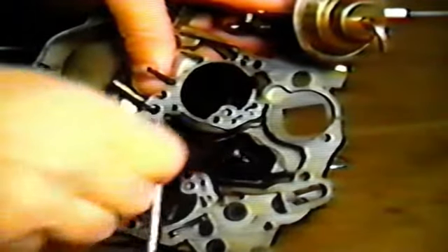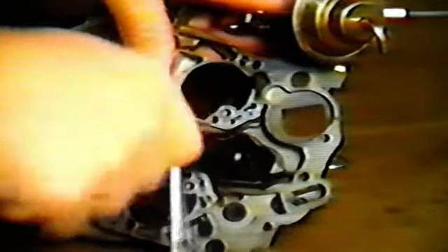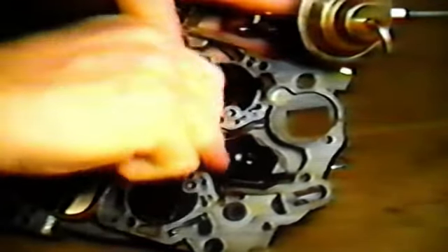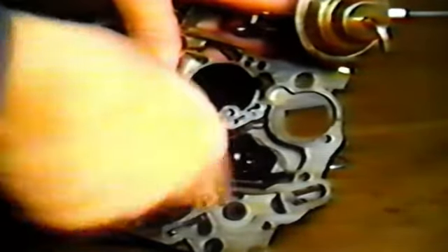After the rich stop plug has been taken out, put the screw back in and tighten it until it just touches the air horn, then back off slightly. Trying to muscle an over-tightened screw could destroy an expensive tool. With the plugs out, you're ready to go on to the bowl of the carburetor.